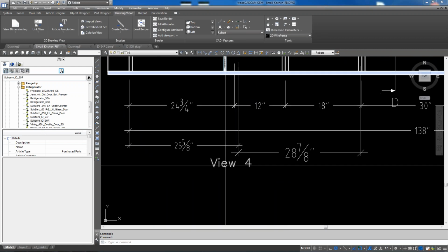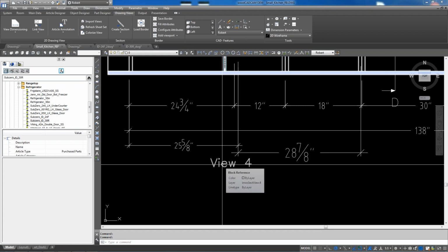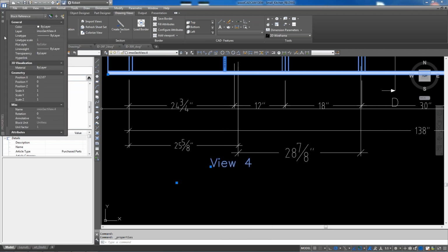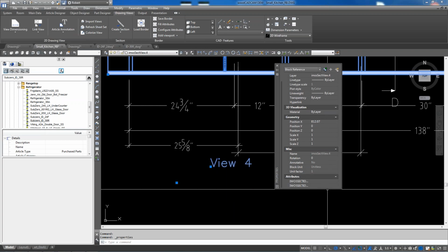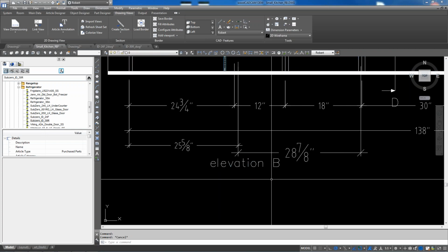Okay, so if we are here, I was wondering how to change the description of the view. Okay, so click on it, right-click Properties. Yep, scroll on down there. Oh, there it is. Just click in there and change it. There's no controls to change what it does automatically. So if you want to change that, then you have to go manually change it. Okay, that works.